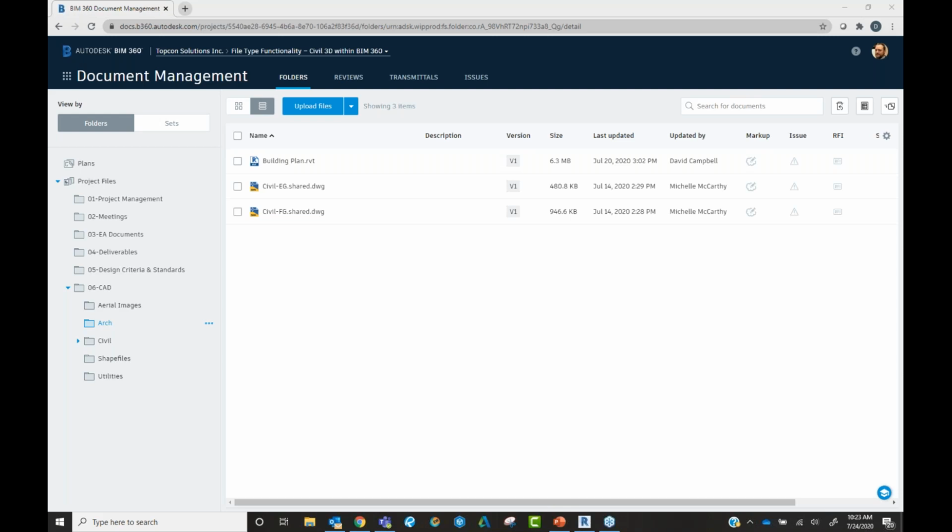Okay, so I'll go ahead and move this to the side a little bit. There we go. I can get out of this. Now, this is a basic 3D model viewer. Whenever you click on these projects, whether it's a DWG, RVT, NWC, what have you, you're going to be able to get in and view these different elements. Now, another important part to that is I can switch between, of course, the 2D and the 3D view. So if I needed to scroll around, look at this, make sure there's my building pad there, so I have a nice indent of where I need to go.